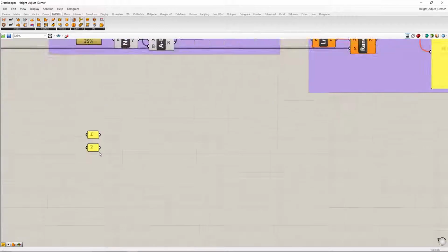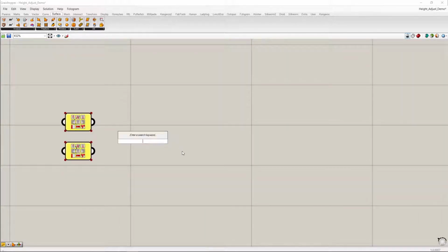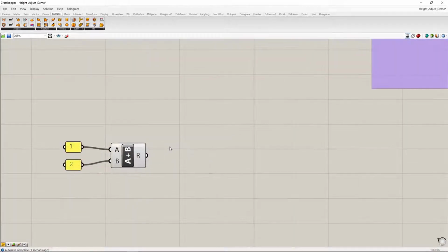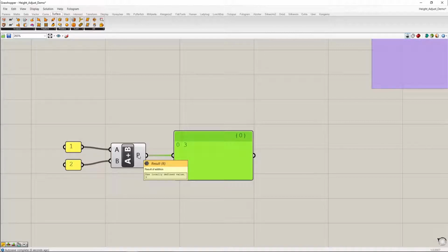You can insert a block by double-clicking anywhere on the background to reveal a search box and typing the name of the block you require into it. Then connect outputs and inputs by dragging a wire between them. Each block, which mostly corresponds to an action, describes to you, if you hover over it, what input it requires and what it can output.